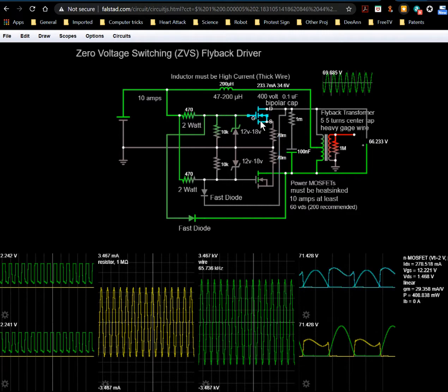So basically, you're trying to charge up the capacitor, which is pretty small, but if you're running this at a high frequency, that's a significant time factor. You've got this Miller capacitance, and then you've got this resistor here, so it's an RC time constant thing. It takes 5 RC time constants to charge this thing up.